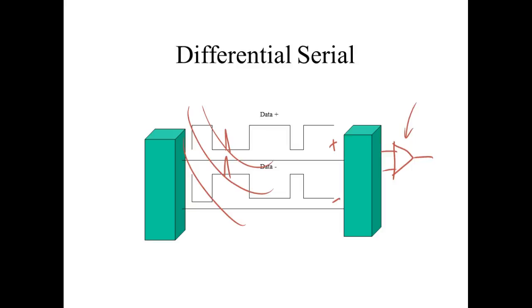And these guys right here are neat. If you take the second electronics course, we get into how differential amplifiers work and all that kind of stuff. But all these guys, all they do is pass the what? They pass signals moving in opposite directions. They don't pass signals moving in what? Same direction. Electromagnetic interference will move in what? Same direction.